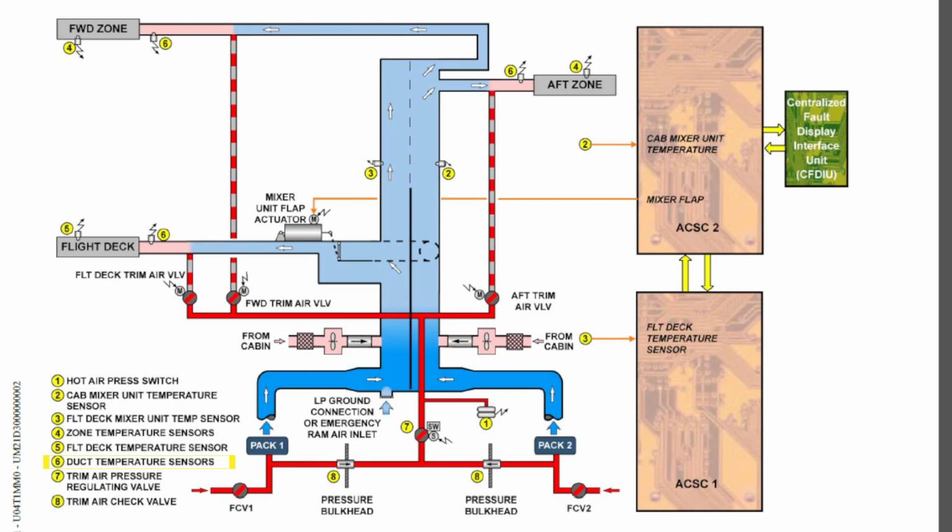The cockpit switch says it's at the auto position, which means it's open, but actually the valve is now closed because of this temperature issue. So you have a position disagreement, and because of that you get the fault light in the cockpit.